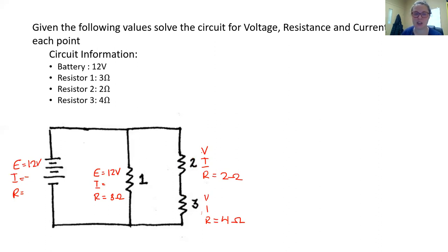Okay, now the first thing I would do is pause and see if there is anything we can calculate. If you look over here, we can use Ohm's law because we have 2 out of the 3 pieces. So current is going to be equal to 12 divided by 3, which is 4 amps. So we just calculated another piece of information. Well, what else can we use anywhere else? We don't know current from the battery, so we can't just subtract to find the current over here.